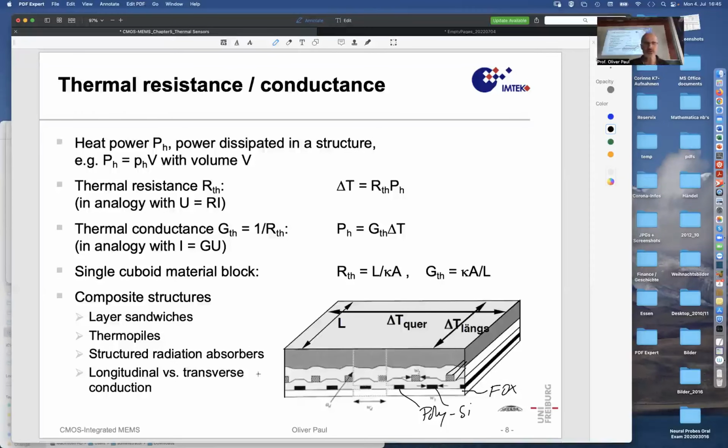So we really see a cross section that we would see at any place where we would cut the structure. And then there's the intermetal dielectric, IMD, and obviously in this design there is no second metal, and then we have the passivation. So we're back to chapter 2, basic technologies. And this whole thing is maybe 6 micrometers or so, order of magnitude, 5, 6 micrometers.